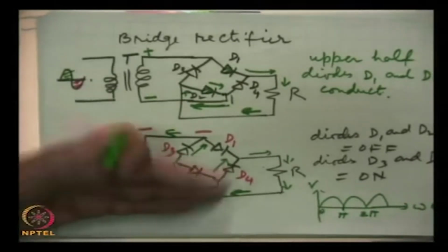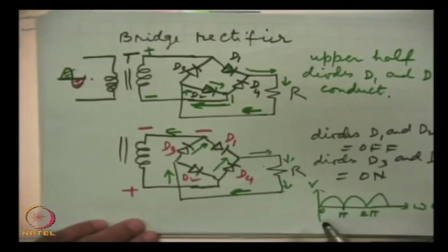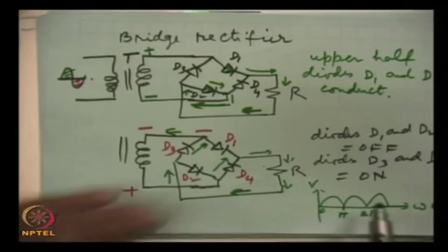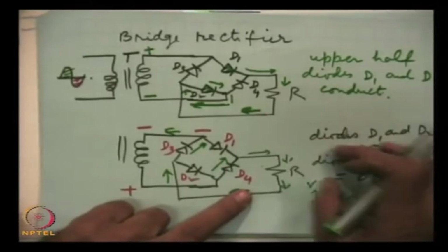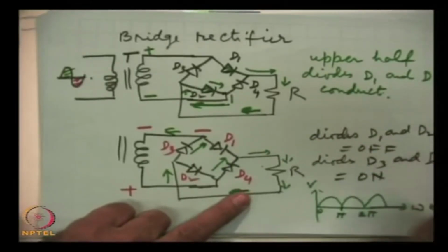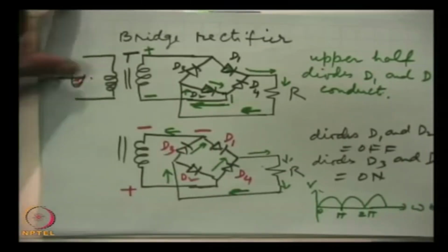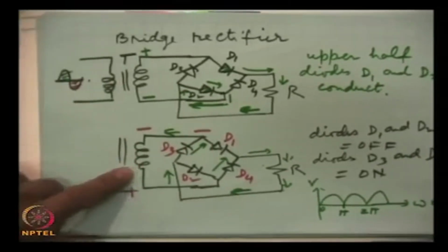So this is again a pulsating DC which will require the filter circuit which we just discussed. This output is connected to the filter here, and the output of the filter will be very much DC. This is much better as compared to the center tapped full wave rectifier. By the way, this circuit is also a full wave rectifier.